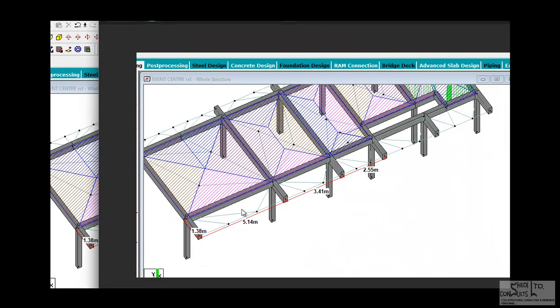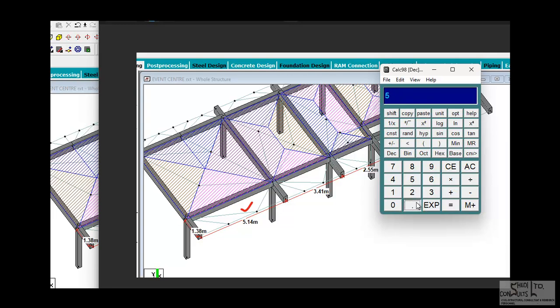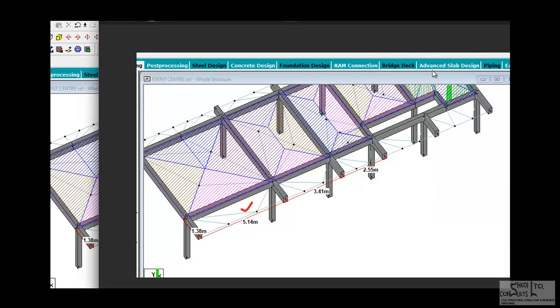Now for this slab, this is a one-way slab panel. It's a one-way slab panel because the aspect ratio of the longer to the shorter side is greater than 2. Okay, so that's 3.72. Therefore, if you analyze this slab manually, and you take a section there, so this is the slab you are to analyze.